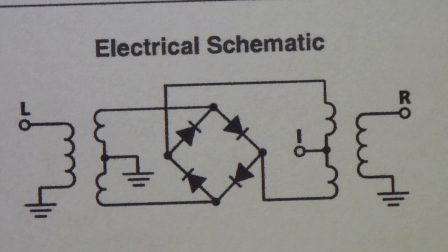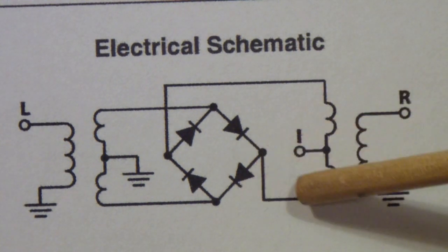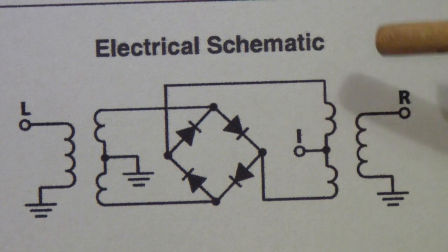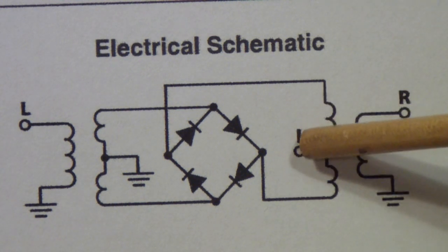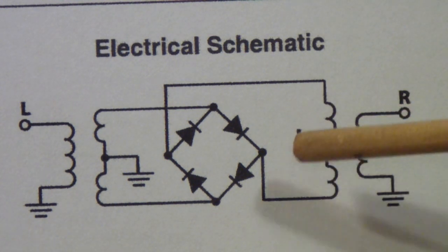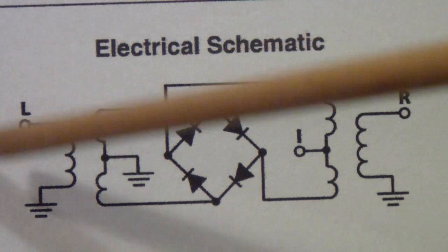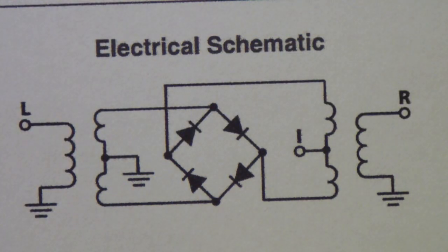Now, for reasons we won't get into here, this is a balanced mixer, and that helps to balance out certain of the components. So for example, the RF signal is much reduced, as well as the local oscillator signal, so that basically at the IF signal the sum and difference are the major components, and the input RF and the local oscillator are much reduced, and we'll see that on the spectrum analyzer in a little bit.